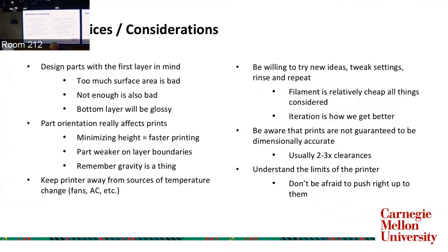Orientation matters. I was talking to some PhD students just the other day, and they printed this part this way instead of this way. And the printer tried to print on nothing, and you get that mess. It doesn't work. Gravity's a thing. So remember, gravity's a thing.